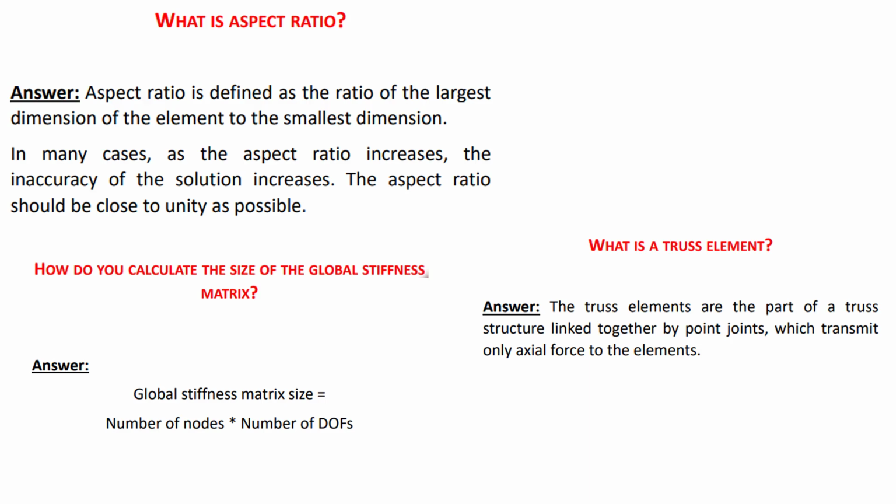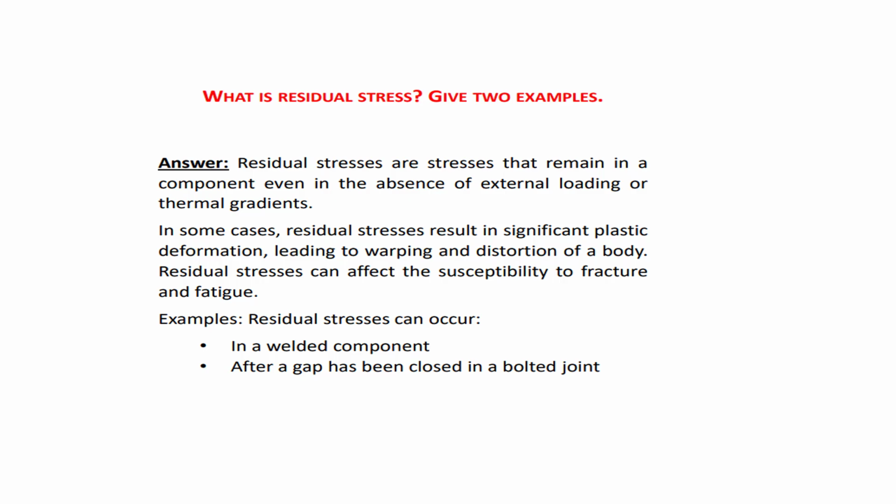Fine. So one more very important term is residual stress. So what is it? It is exactly the stress which will remain in a component even in the absence of the external loading condition, thermal gradient we can say. In some cases, residual stress results in significant plastic deformation, leading to warpage or distortion in the body.